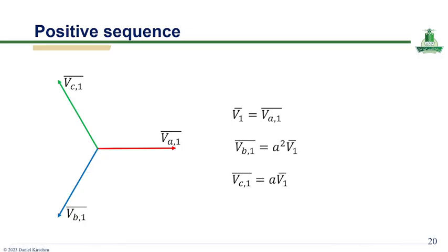So the positive sequence represents the normal operating condition of the power system, similar to the balanced condition, and it is the only component present under balanced conditions. This makes it especially important for standard system analysis, load flow studies, and understanding how the system behaves under ideal conditions.